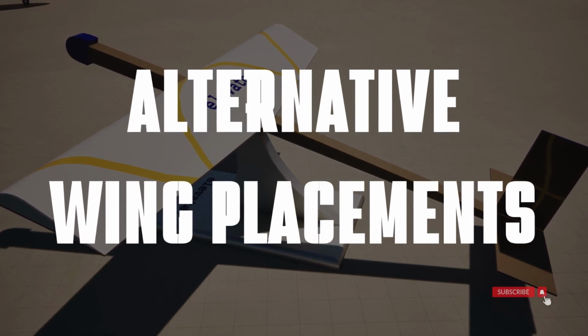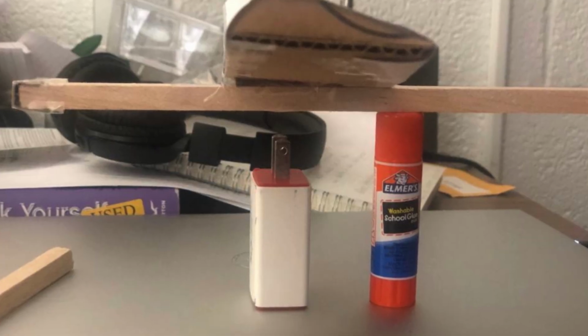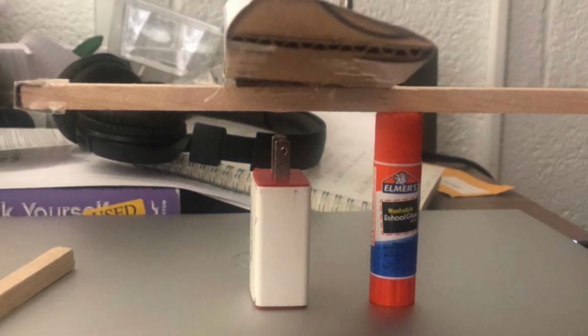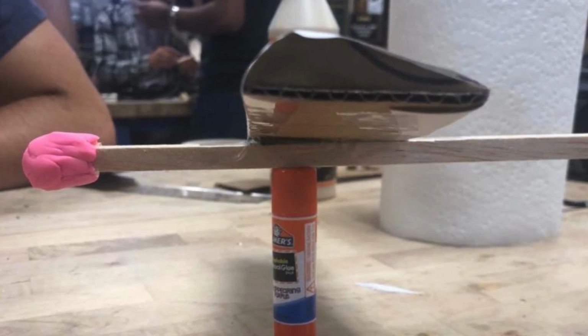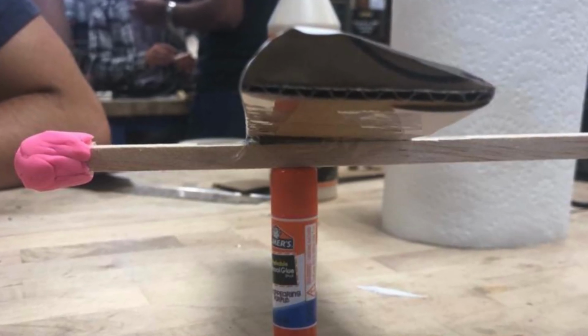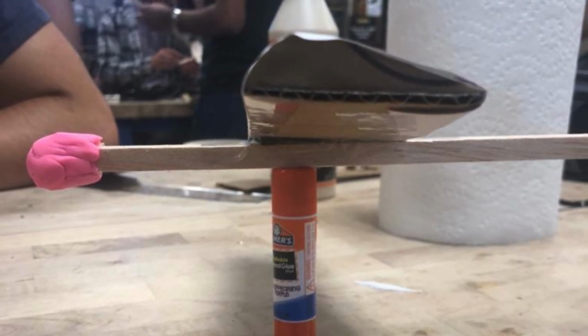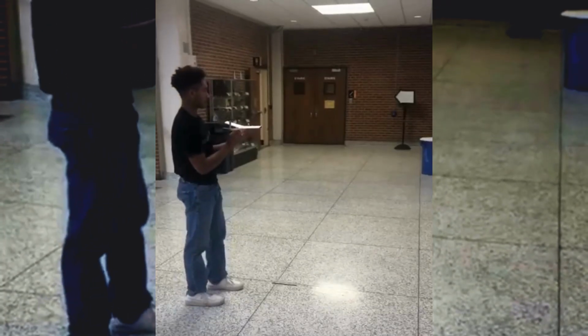First, I tested the CG placement using a glue stick to try to balance the plane over 1/4 the wing chord. What I immediately realized is that the wing shouldn't be close to the nose. Also, what affected the CG the most was adding mass using Play-Doh rather than moving the wing. So in the end, I decided to place the wing near the middle of the fuselage and add mass to the nose to compensate for any imbalances. Now it was time for the test flights.